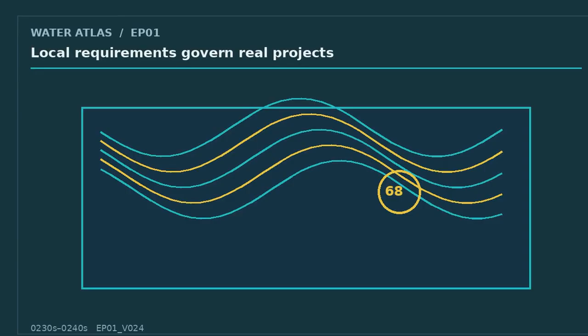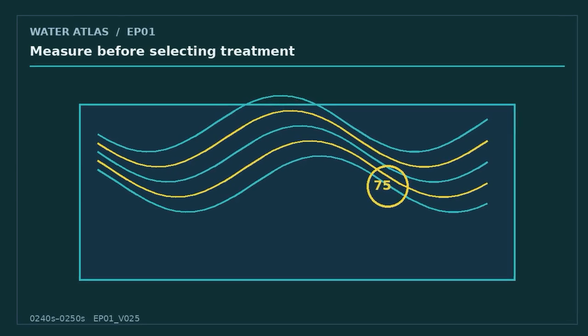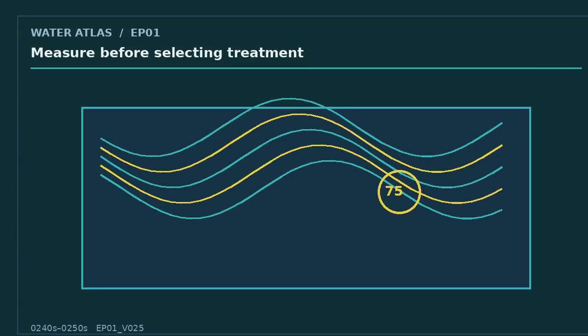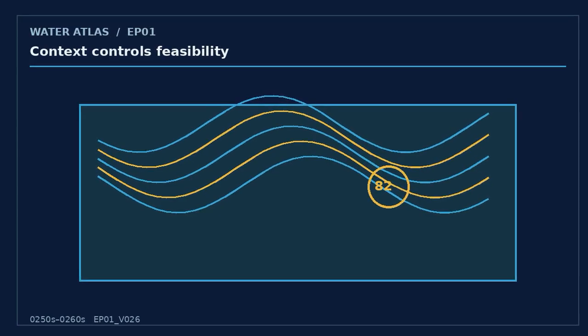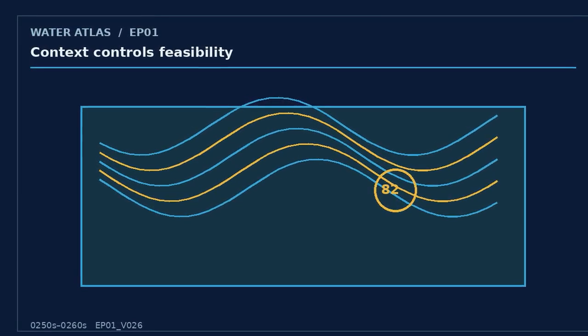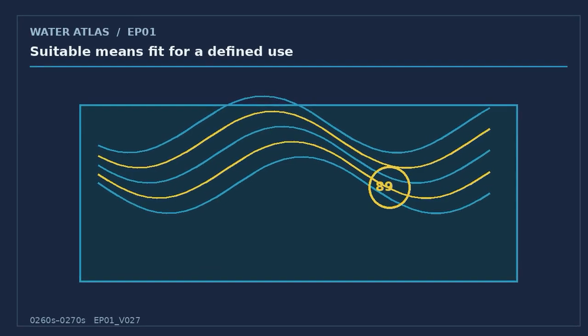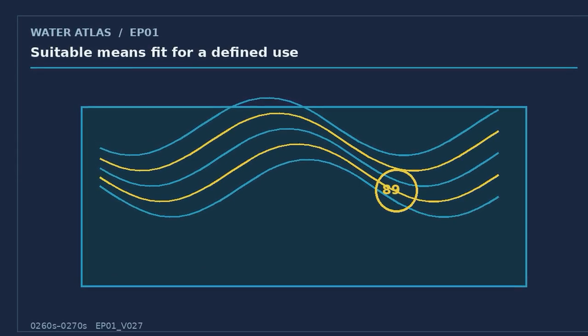After preliminary treatment, primary treatment uses gravity. In a primary clarifier or sedimentation basin, heavier settleable solids move downward to form sludge, while floatable materials such as grease can be skimmed from the surface. The clarified liquid moves forward, but it still contains dissolved and fine suspended organic matter, nutrients, microorganisms, and trace constituents. Primary treatment is an important separation step, yet it is not usually the whole answer when the goal includes robust environmental protection or controlled reuse.